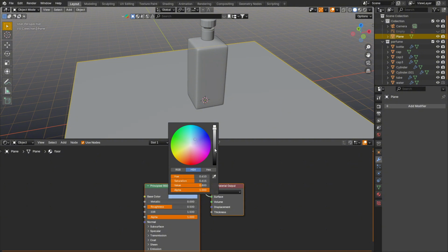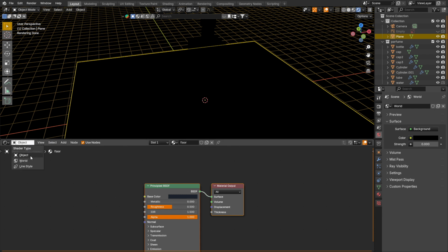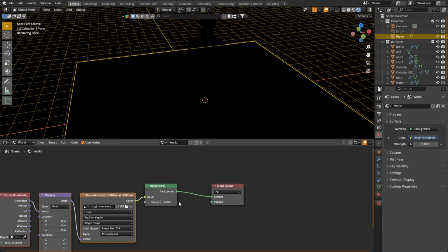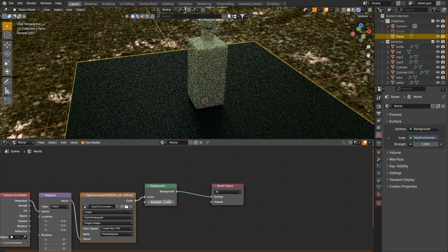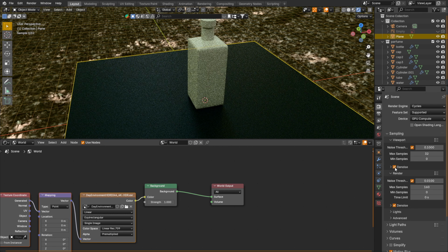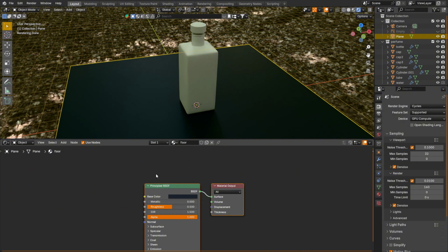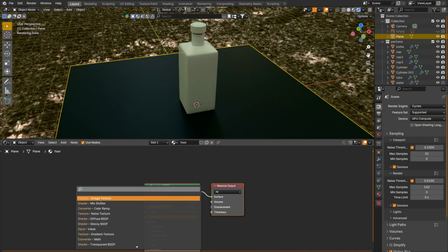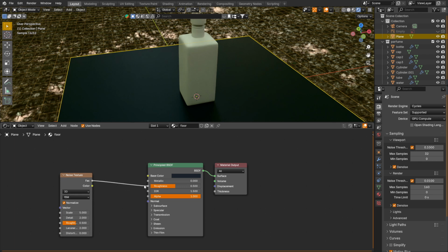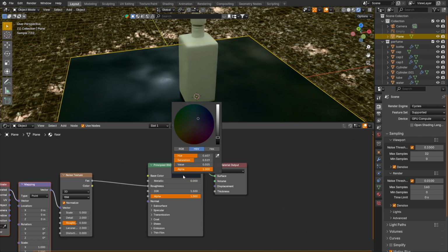For more clarity, let's go to render mode and I'll connect the HDRI map with lighting, half forest and half sky. I'll check the box next to denoising in the viewport. And so we return to the floor material. Let's add a noise texture, connect it to roughness and press Ctrl+T to add texture coordinates and mapping. To do this, you must have the Wrangler add-on enabled.